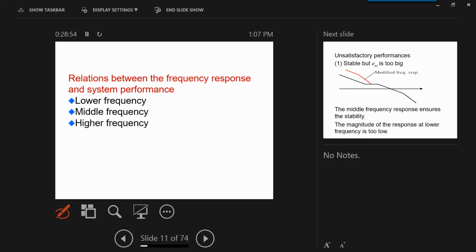When omega goes to 0, when we talk about step response error, right? The step response is a constant. It has 0 frequency, right? So when we talk about steady-state performance, we are talking about low frequencies. When time goes to infinity, 1 over infinity is 0. So when we go to low frequency, this is where we look at the steady-state performance.